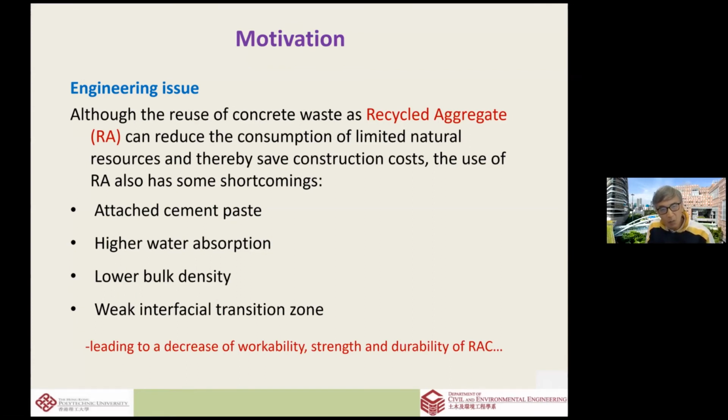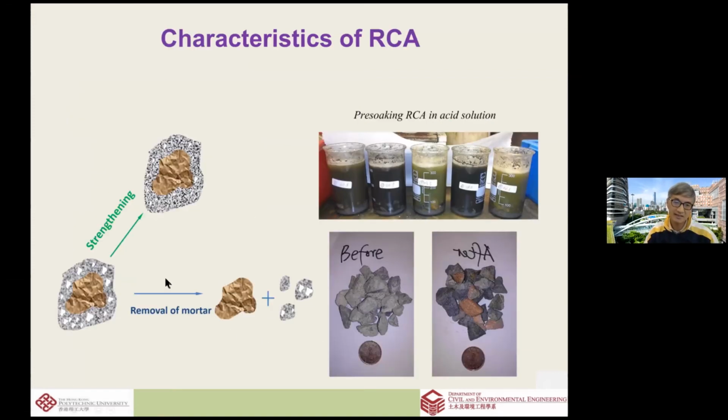What we have been doing, and why we are interested in carbonation, is the recycled aggregate itself after crushing. Okay, this is a schematic of a recycled aggregate. You can visualize it as about 20 mm in diameter. There is the natural aggregate inside, and there is the mortar, the old mortar from the old concrete, old cement paste as well as sand, covering the natural aggregate.